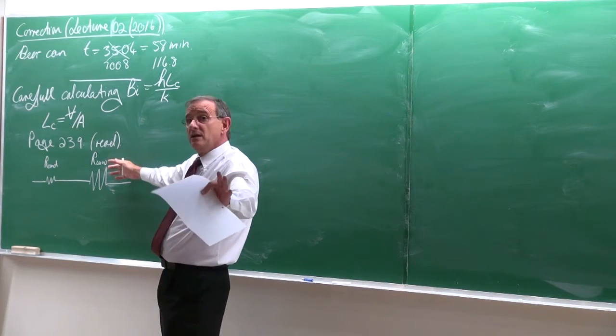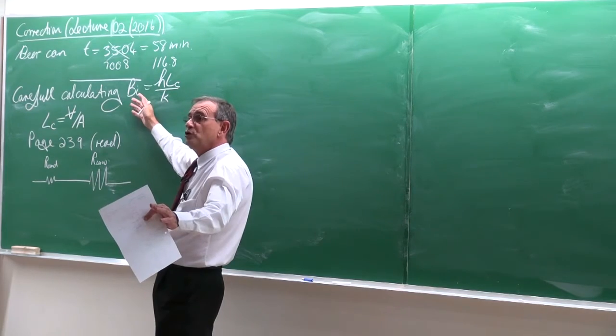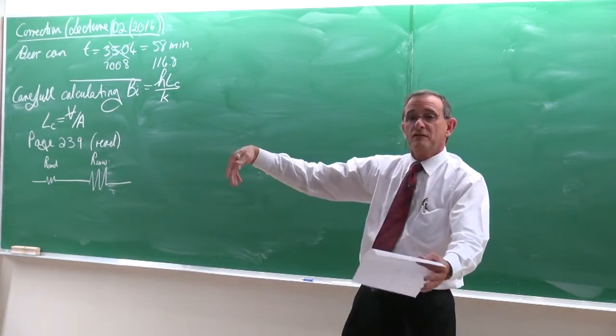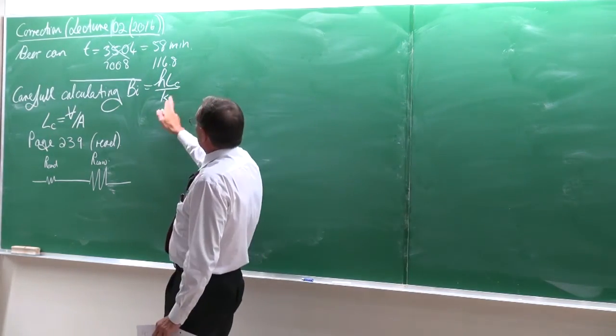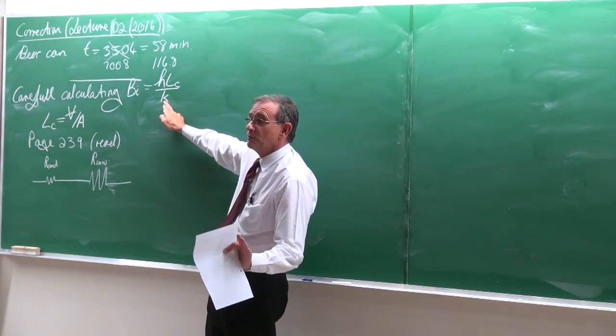But sometimes, depending on what I'm asking you, you can start a calculation and it wouldn't be possible for you to calculate the Biot number. Okay, so that can also happen. So you will have to make the assumption that maybe it is, but sometimes it will also be possible to see it's not even going to work. I shouldn't even try the lump system approach.